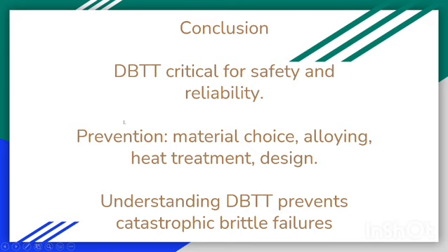I missed about design. Sharp edged design makes the metal brittle, so we need a curved design in the metal. It reduces the stress and the metal behaves ductile.